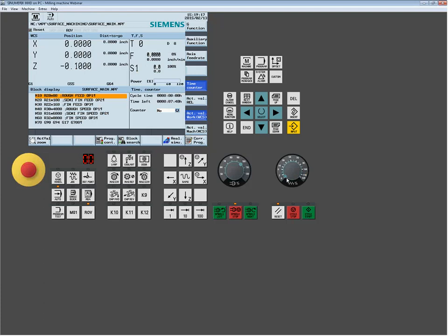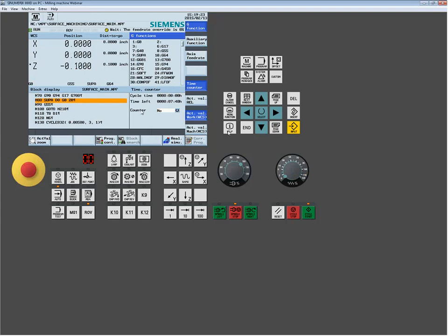When I first start up the program, I'm going to turn on my G-code function panel right here and hit cycle start. I'm still up; haven't gone into that program yet. I have a G64 enabled. That's our base corner rounding function.